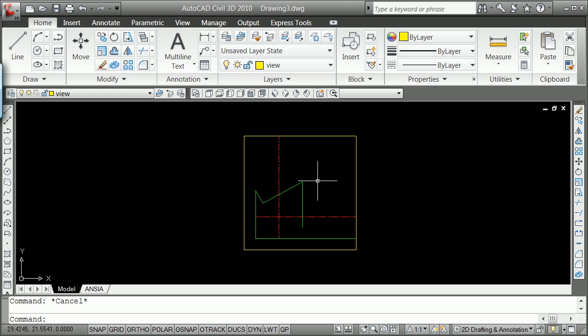So that's the difference; mathematically you can actually compute all of these, and I will do this in the next short video. For those of you, as I mentioned before, if you know the direction of a line, you know the reverse azimuth or the back azimuth, you add the turned angle and you get the next direction of a line. So I'll go through the mathematics and the way you can compute this stuff.